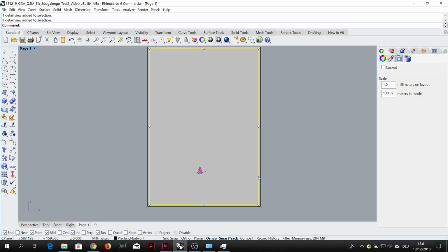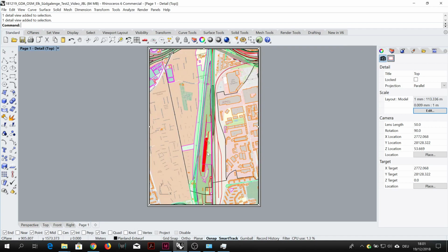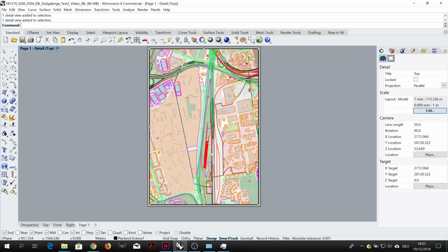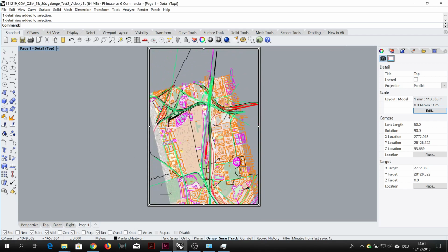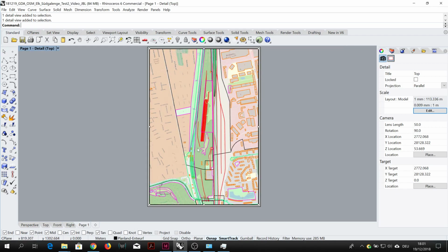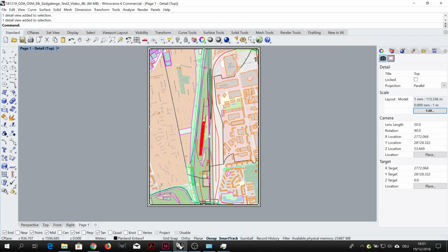So we double click the frame, and now when we scroll, you can see that the plan moves within the frame. And to pan left and right, remember it's right click and drag the hand tool. And we're going to just scale the plan so it's central to the A1 sheet of paper. And roughly everything's fitting on there.